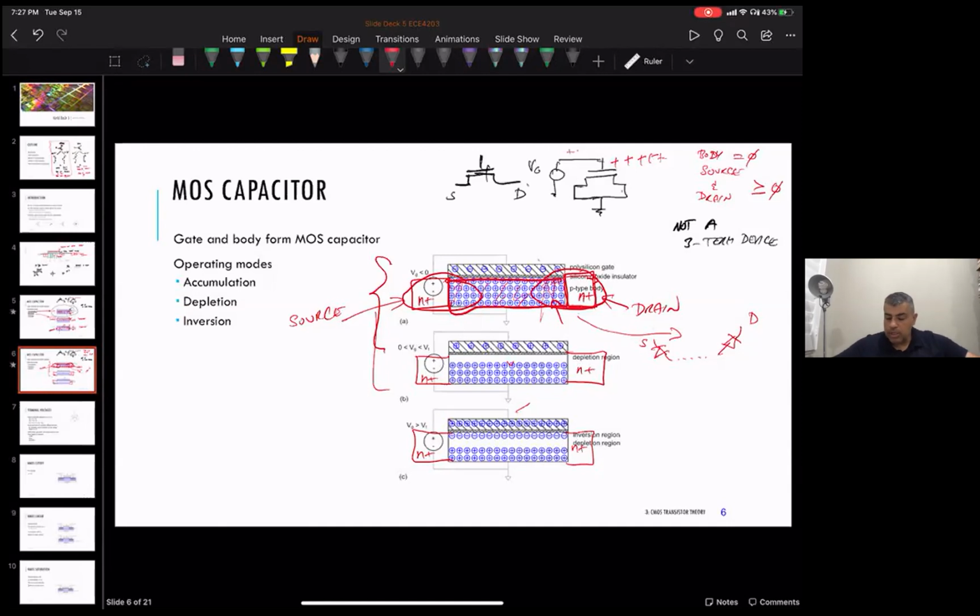If we assume all that, which is how our circuits are going to operate, then in these two cases the drain and source diodes to the channel are going to be reverse biased. So you won't get any current going one way or another. It just can't happen because of those diodes.